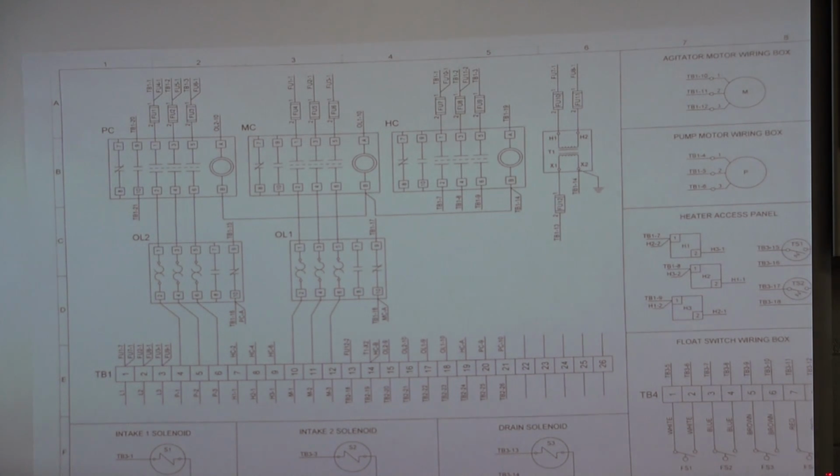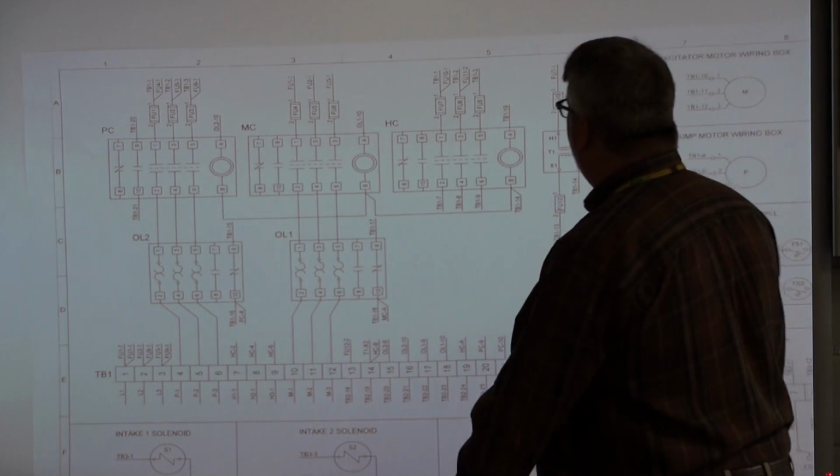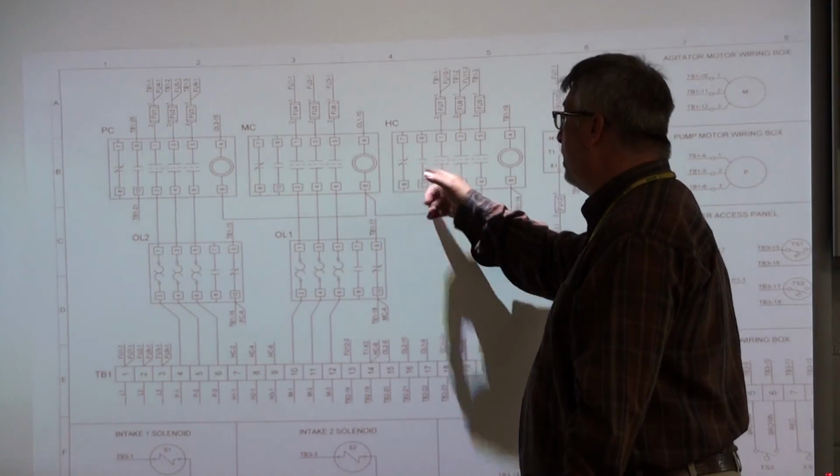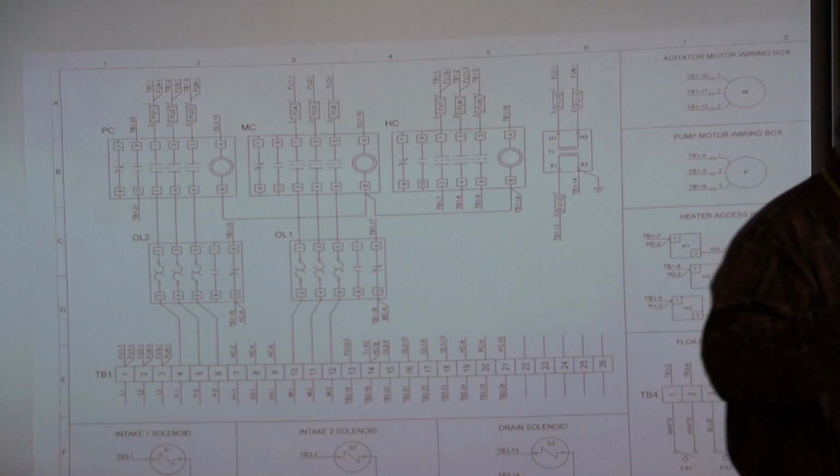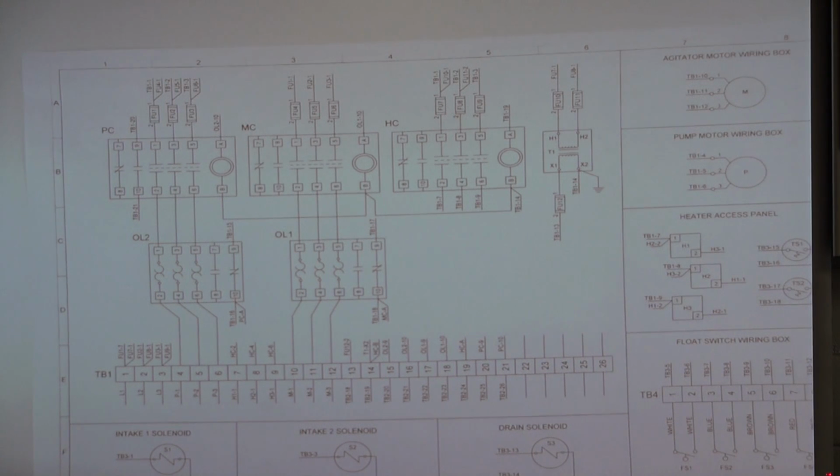And if you look at this contactor, it's got some normally open, normally closed, and normally open contacts there that have a set state when the contactor is engaged or when it isn't engaged. So we can look at a contactor through those outputs and determine whether it is engaged or not.